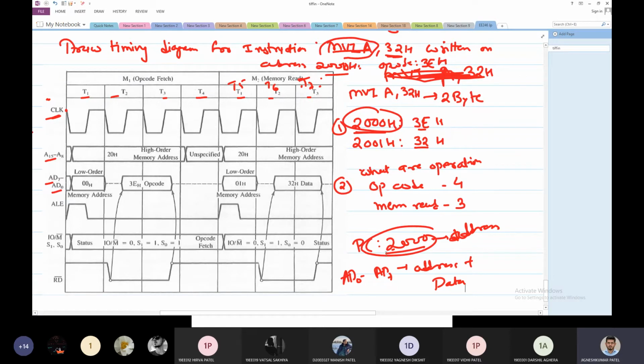So what appears on the address bus has to be shown in the timing diagram. Actually, I am drawing this diagram to understand when and where things will be available. So first, data would be available on the address bus. See how to draw this. I'll make this transition, whatever was there earlier, I don't know. So this is a transition from something to a new thing.